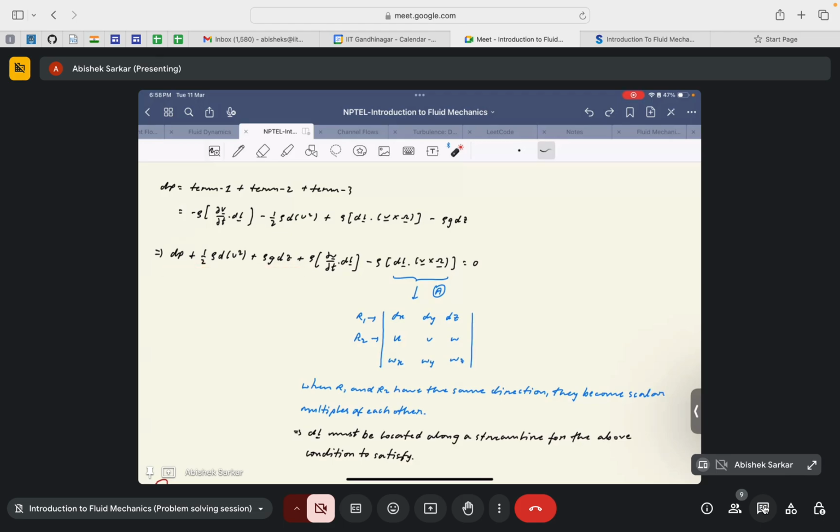But the other two terms, the unsteady term and the vorticity term, are inherently present when we start with the governing equation of motion, the Euler's equation. But there are certain criteria or certain approximations that we can make that will help us to avoid these terms.